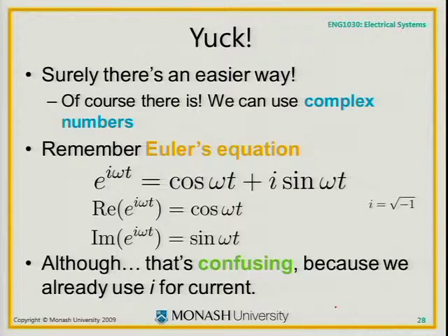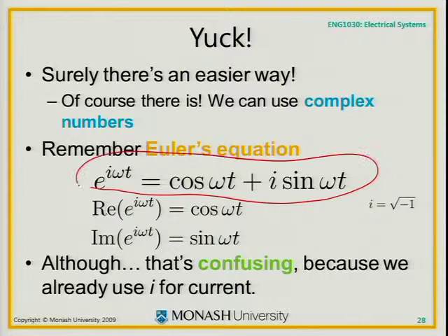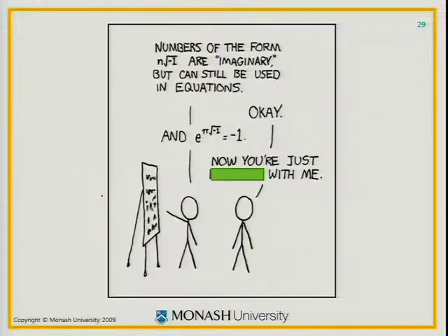We can use complex numbers because a complex number has an amplitude and a phase. We use a complex number instead of a sinusoid. The amplitude of the complex number is the amplitude of the sinusoid. The phase of the complex number is the phase of the sinusoid. There's the direct matching between complex numbers and sinusoids. So instead of trigonometric identities and playing around with sinusoids, we can use complex numbers and complex arithmetic. This thing is, of course, critical, how we move between polar and rectangular forms. Euler's formula or Euler's equation. But there's one catch. I'll just let you read that.